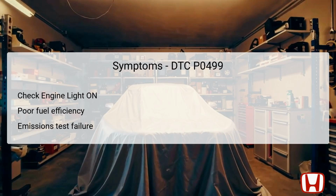When DTC P0499 is triggered, several noticeable symptoms may manifest. The most immediate sign is typically the illumination of the check engine light on the dashboard, alerting the driver to an issue within the vehicle's emission system. Additionally, drivers may experience poor fuel efficiency, as the malfunctioning canister vent valve may disrupt the proper functioning of the EVAP system, leading to increased fuel vapor loss.